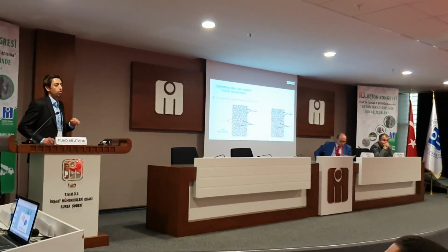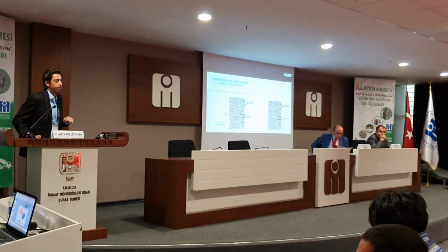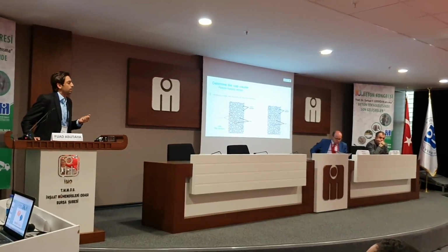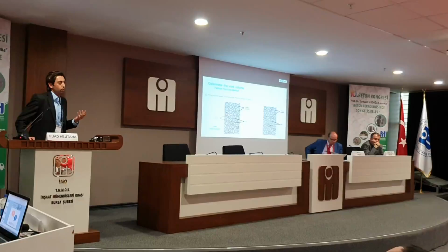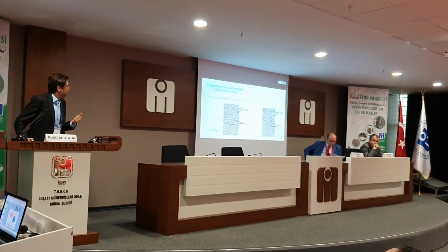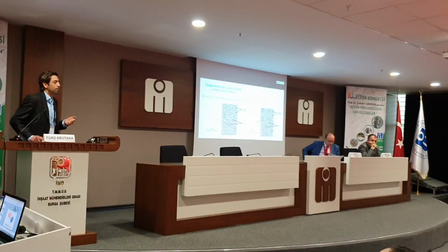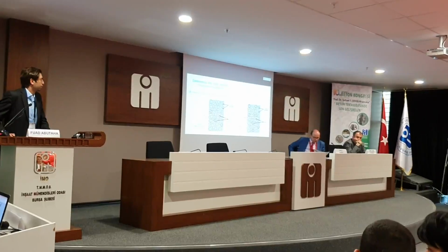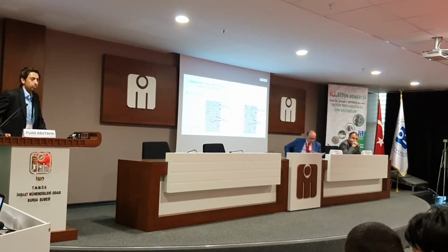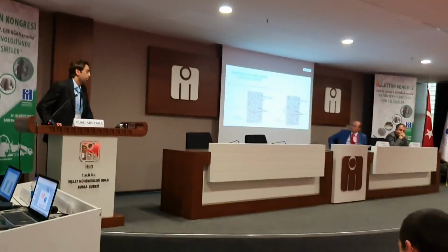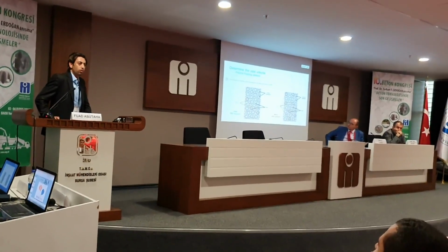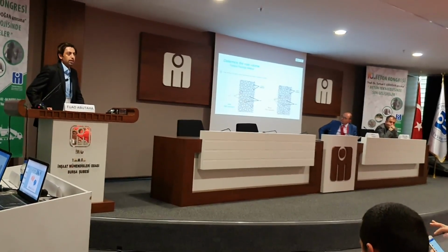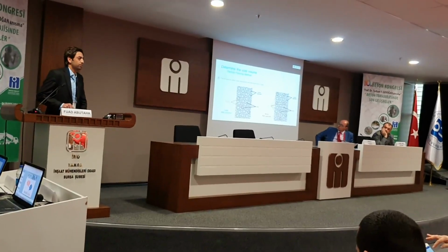Of course, a low level of POC coarse aggregate does not consume as much water. The water used with low levels of POC content will be less than when we use a high volume, a high percentage, of POC coarse aggregate. So the amount of water used with low levels of POC was lower than the water used with high percentages of POC content in the mixture.